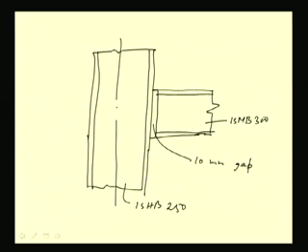Now we will provide seat angle and the cleat angle with some nominal dimension of cleat angle and the seat angle which has been found from the design. This is ISA 150 by 115 by 15, and here in each row 2 rivets are there.